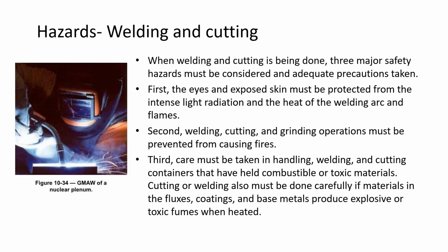When welding and cutting is being done, three major safety hazards must be considered and adequate precautions taken. First, the eyes and exposed skin must be protected from the intense light radiation and the heat of the welding arc and flames. Second, welding, cutting, and grinding operations must be prevented from causing fires. Third, care must be taken in handling welding and cutting containers that have held combustible or toxic materials.